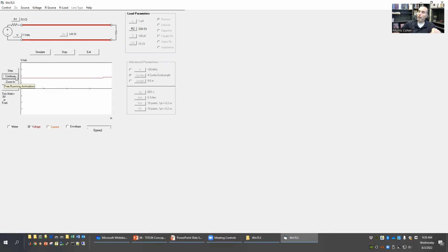Now, bear in mind, waves can be negative, right? So waves can reflect with a negative coefficient, which would basically remove voltages, but that's still built on top of whatever was there. So after a very long time, we've got this voltage to current ratio, which is not the same as E0 if we look at the net total.